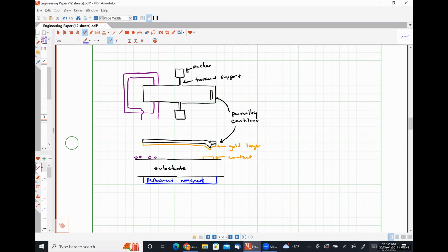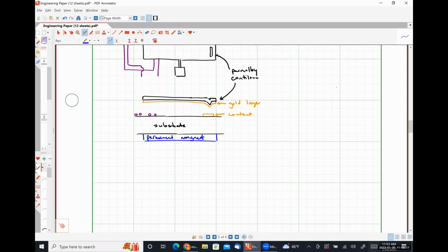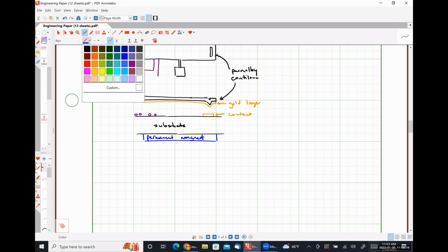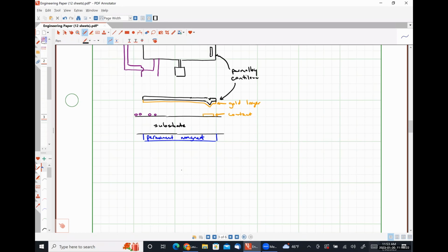So this is an example of really two things we haven't talked about yet. Bimorphs, so that's just a structure made of two different materials. So this would be a bimorph cantilever made of permalloy and gold. And then it's also bistable, meaning that it will be stable in an on position and stable in an off position. And then the switching thing is point of instability, okay? So the bistability of this switch means that it's 2 points that it wants to be in. It's 2 operational points.